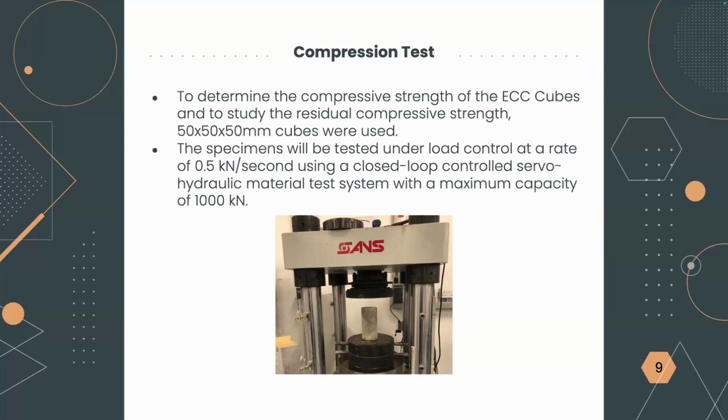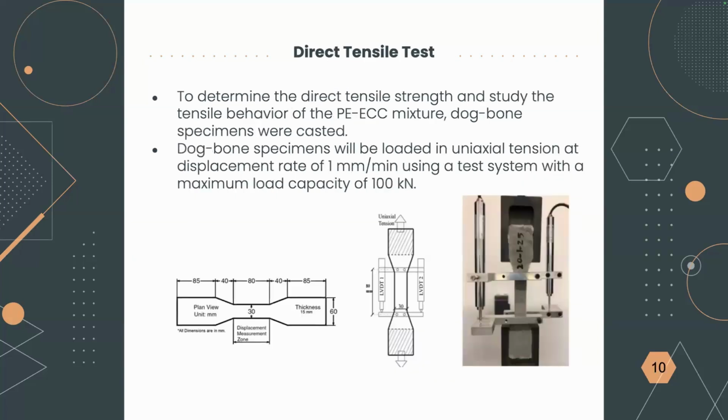So you have the ability to use 2 specimens in this machine, either a cylinder or a cube. Cube comes in the dimension, for example, of 50 by 50 by 50 millimeters, or the cylinder can come in 100 millimeter diameter by 200 millimeter height. So you can use either of these 2 specimens. So what would happen, we would place our specimen here, and the bottom part will start moving upwards. And once it touches the surface of the upper part, now we are ready to do the test.